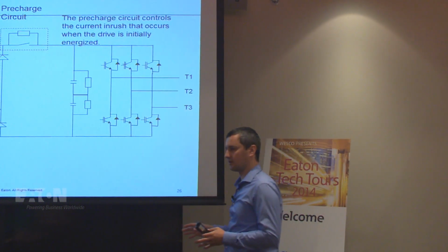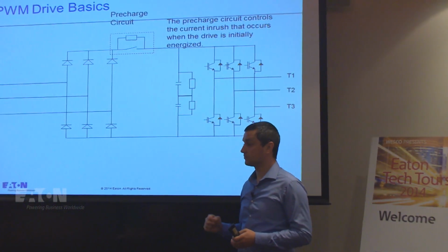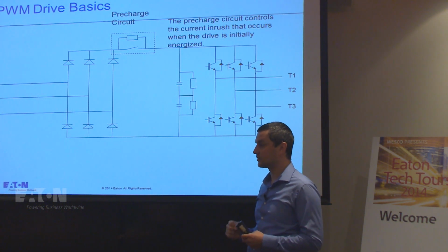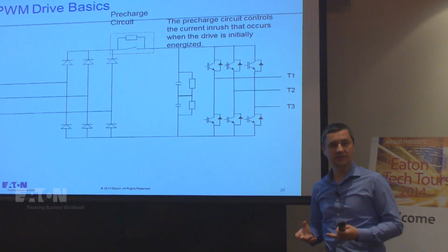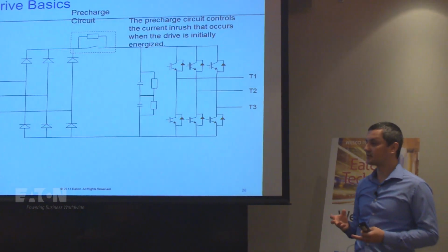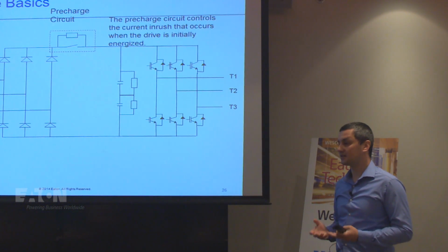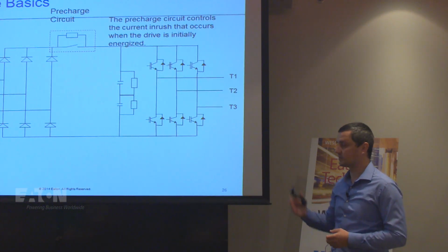Some people I know, electricians in the field out there, like to connect and disconnect the drive. If you're doing that too fast and too often, you're going to burn that resistor. Most of the time, that resistor is directly on your PCB board, okay? It's not easy to replace, so sometimes you have to replace the entire board just because of that.